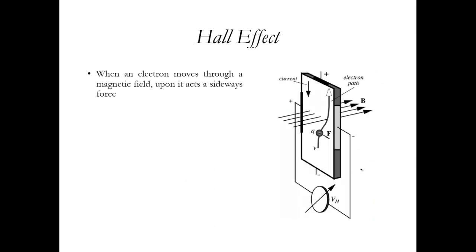So this is again a line diagram where it shows the magnetic field direction and the forces that are acting on the electron as it moves through a magnetic field, let's say from a permanent magnet. So this was the original current flow through this conductor, and because of this magnetic field there is a current in the perpendicular direction that flows through this, which is called the Hall voltage, or the transverse voltage, that is developed because of the Hall effect.